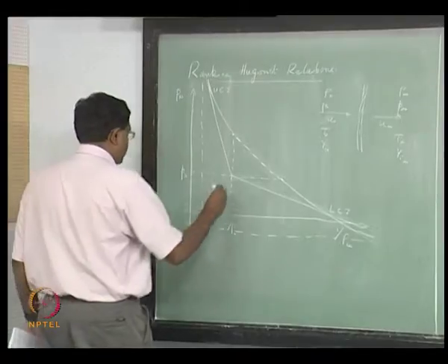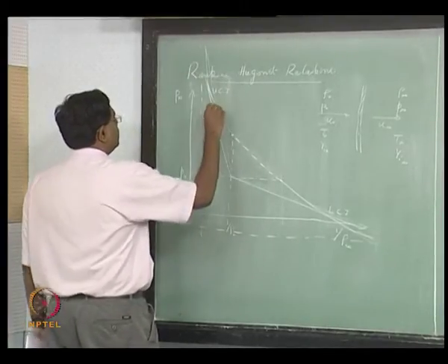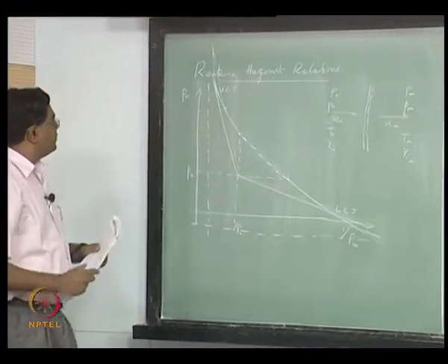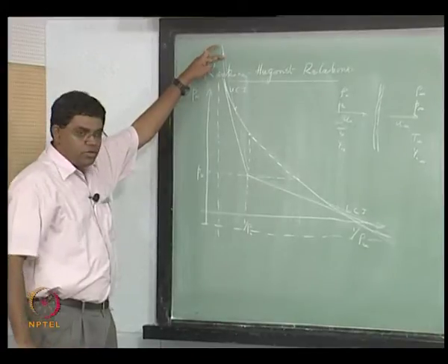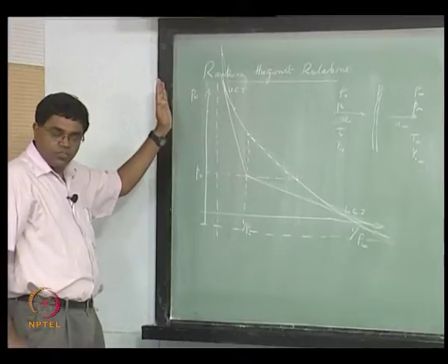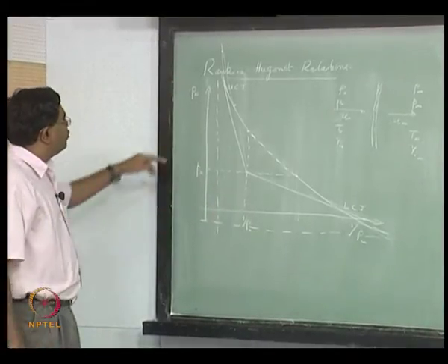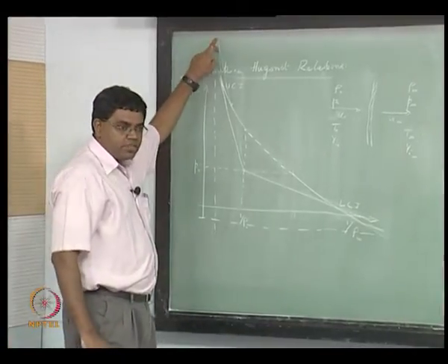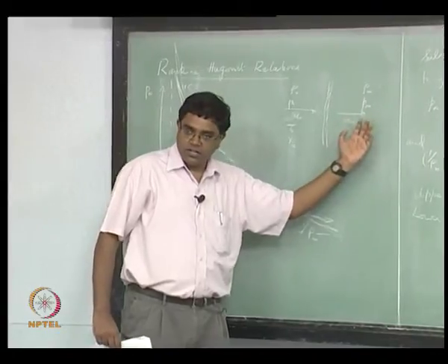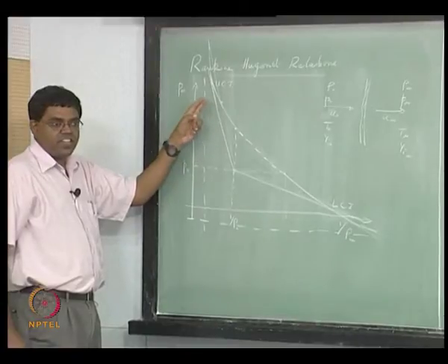So if you now have any detonation, right, you can now have a solution here and here, and this is something that's going to correspond to a very high pressure and very high density as well, very low 1 over density. Therefore we are expecting it to get a lot compressed and therefore a lot decelerated, so it can get down to subsonic speeds over here, and on this side it's not going to be that much compressed, therefore it's not that much decelerated.